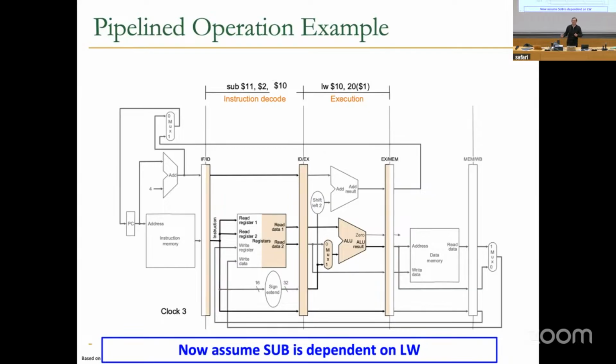We built this in combinational logic, right? You have an equality checker. You have one equality checker that compares this to the destination register that's coming from here. So there needs to be some arc from here to here that gives the destination register ID. Here, here. So 3 equality checkers. Not only that, you should also check whether the instruction that is writing to that register is actually writing to that register, meaning there's a write signal to the destination register. You should also do the check for the other source. So there needs to be 3 more equality checkers.